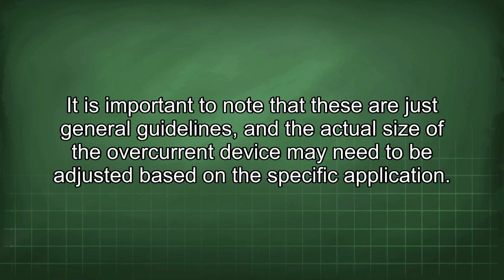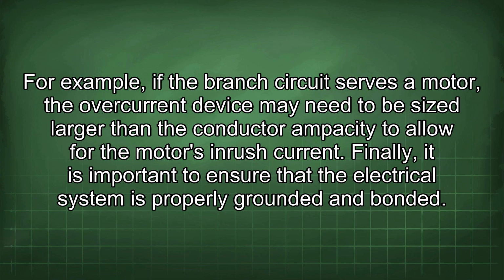It is important to note that these are just general guidelines, and the actual size of the overcurrent device may need to be adjusted based on the specific application. For example, if the branch circuit serves a motor, the overcurrent device may need to be sized larger than the conductor ampacity to allow for the motor's inrush current.